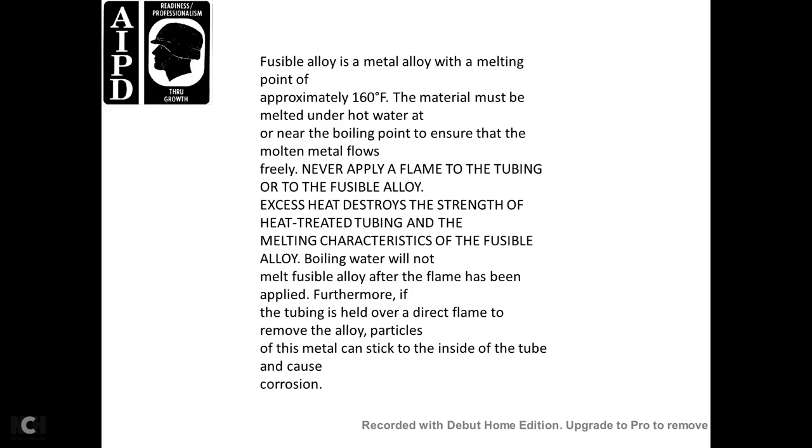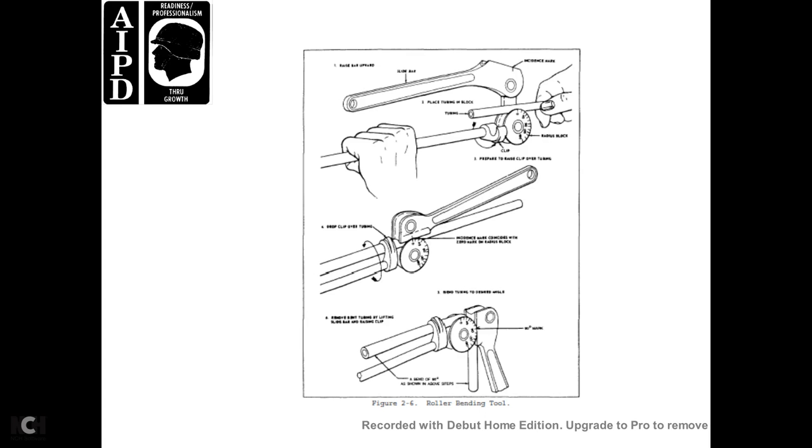Boiling water will not melt fusible alloy once the flame has been applied. Furthermore, if the tubing is held over a direct flame to remove the alloy, particles of the metal can stick to the inside of the tube and cause corrosion.